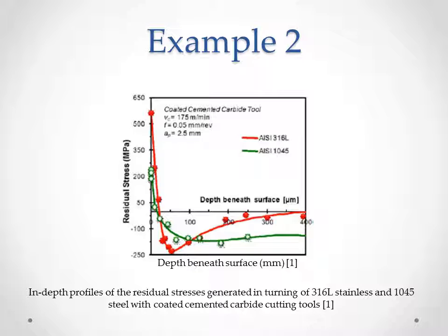So with the steel, yes, it starts out at a pretty high stress, but it levels out fairly quickly to basically a straight curve. Versus the stainless, where we have a well at essentially around maybe 75 millimeters, and then it comes back up to quite a bit less at the surface. So just that difference between the subsurface and the surface inherently leads to, as we've been discussing, problems in the material, residual compressive stresses, and this can lead to a lot of problems versus the fairly straight curve of the regular steel.